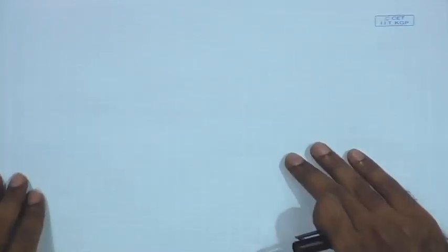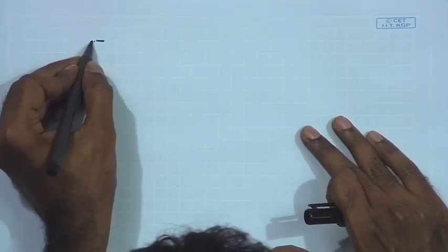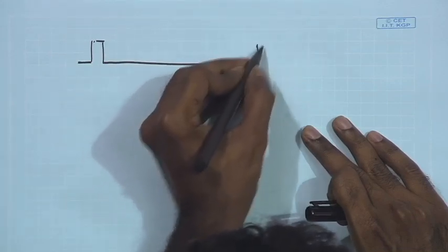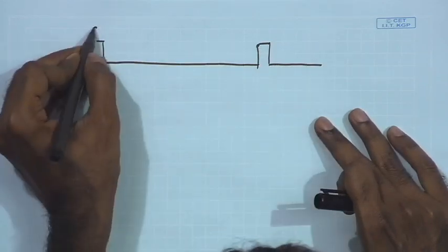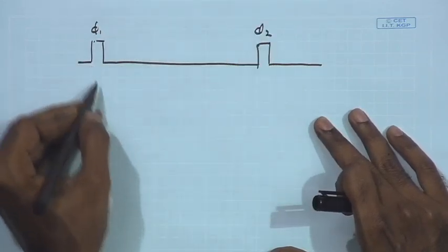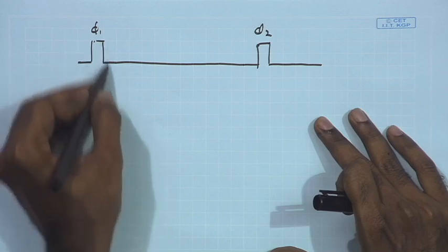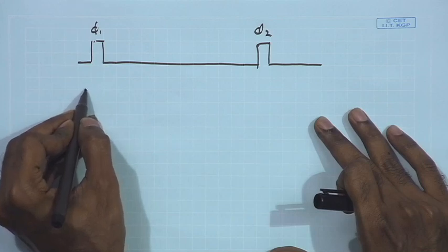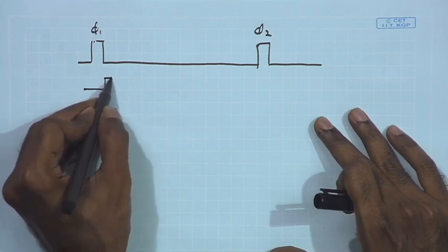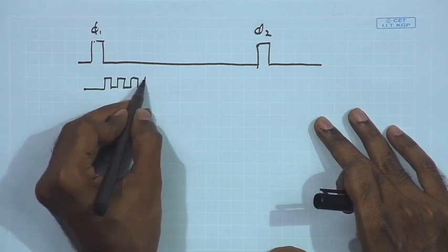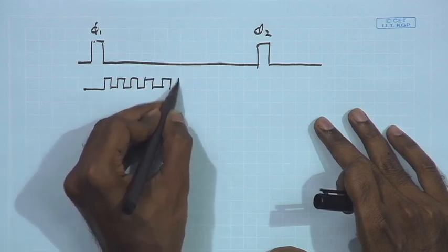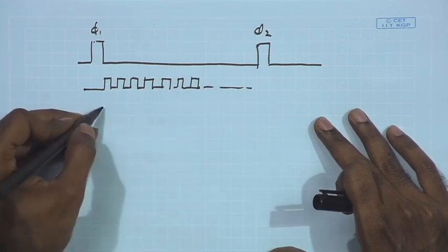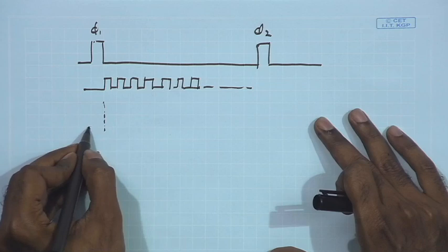So if I look at the waveform that we are going to require, once again reverting to our two phases, phi 1, phi 2, we are supposed to start the counting operation say at the negative phase of phi 1. So you may have the counter getting started over here, and we expect that the ramping voltage is also going to start at the negative edge of phi 1.